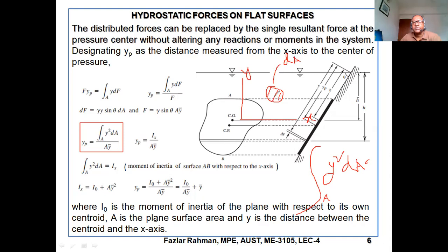And here's a CG, right, at this point. So this location of CG, vertical distance is y and horizontal distance is x. Now, you take the moment of this area. I will take the moment. Force into distance equals moment. Right, now we have to take area into distance. So distance y into area. This you are getting, the moment of area.